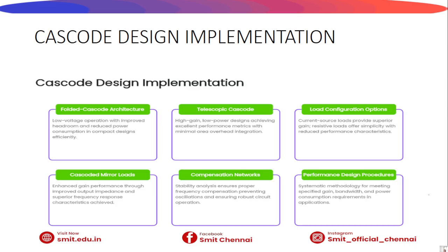We will often see it implemented with MOSFETs or BJTs, and the key is to ensure proper biasing to set the operating points for optimal performance across voltage and current.